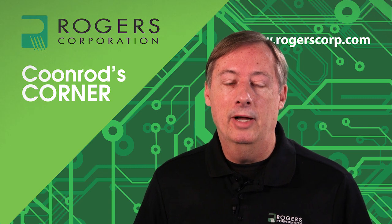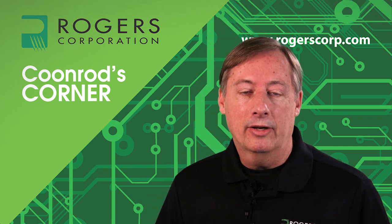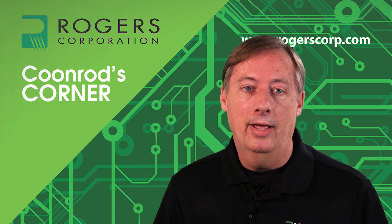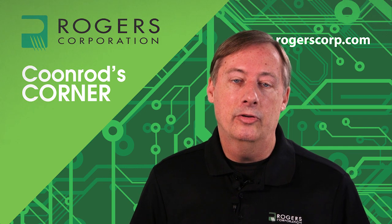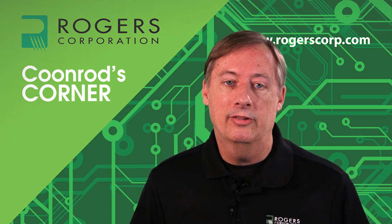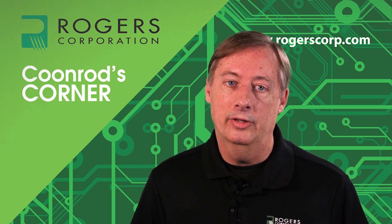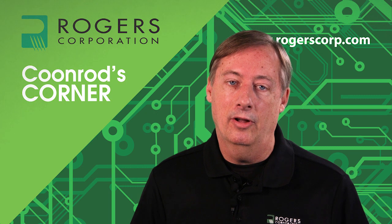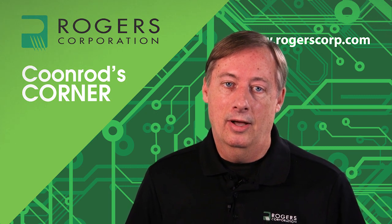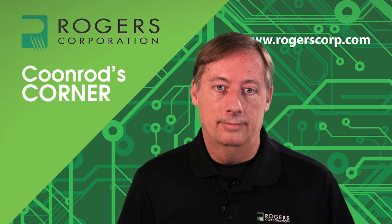Now, some of the things to be mindful of are probably obvious for circuit fabrication, like the conductor width and how well that's controlled, as well as copper plating thickness and a variety of other things. But in the next few graphics, I want to explain in a little more detail some of the tricks that you need to be mindful of when you really get to higher frequency. An antenna designed at millimeter wave frequency is typically more difficult than at microwave frequencies for a variety of reasons, and I'll touch on that in the next few graphics.